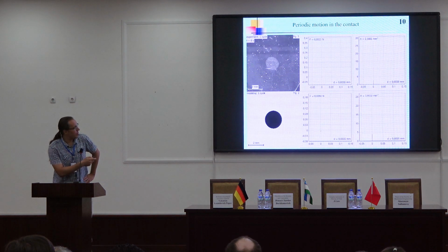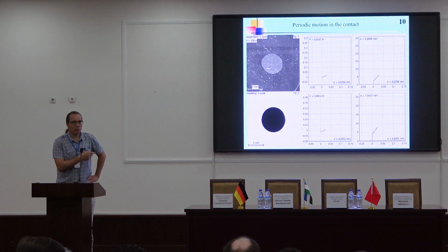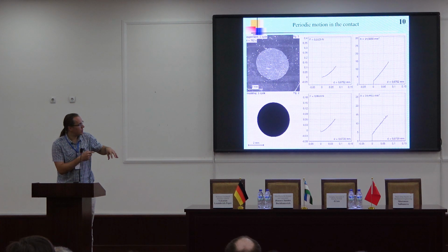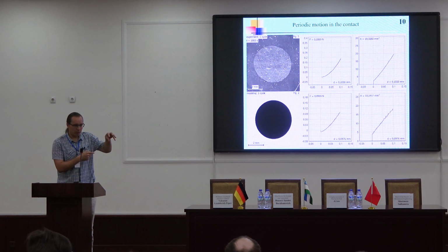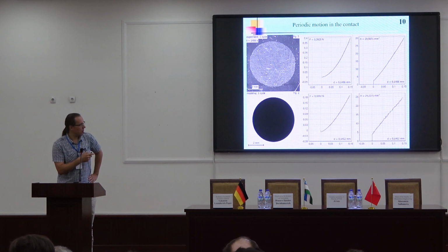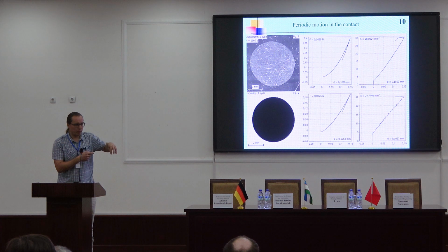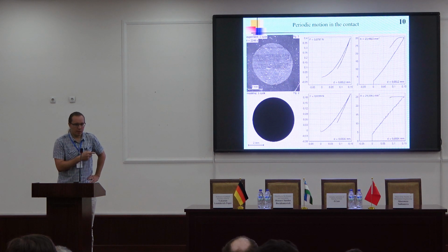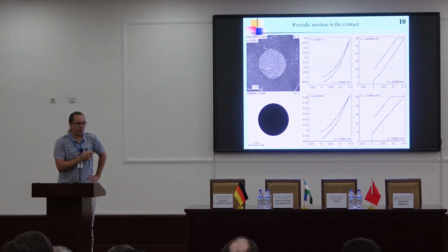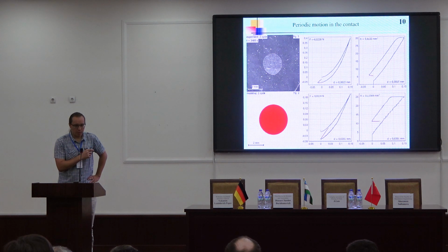And here is also an experiment with periodical motion of the indenter. We performed indentation to the maximum indentation depth of 0.15 millimeter. Then we performed detachment, but not to full destruction of the contact. And then we changed once again the direction of motion of our indenter. It's a cyclic motion of the indenter in JKR. In principle, in this case, we did not observe any hysteresis. And if we did not observe hysteresis, there is no dissipation of mechanical energy.